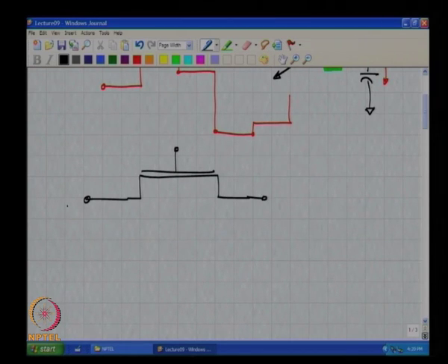So let us say this is Vin, this is VDD, and this is the sampling end of the switch. This will also be equal to Vin. All right. I am assuming a held input, so that the current through the MOS transistor is now 0. Is this clear to everybody? The nature of the difference between a continuous time input and a sampled and held input. Okay. Now why is a MOS transistor conducting?